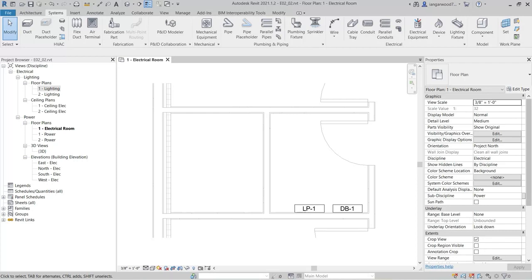In this project, we will add equipment to an electrical room, create lighting circuits, and then review the connection options when creating circuits between panel boards. Finally, we will create and use panel schedules to understand the difference between creating circuits using feed-through lugs and connection to a breaker.